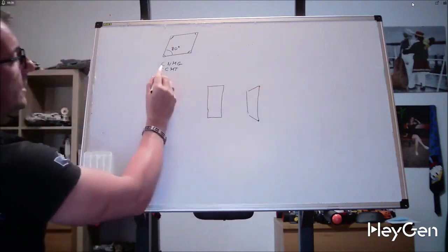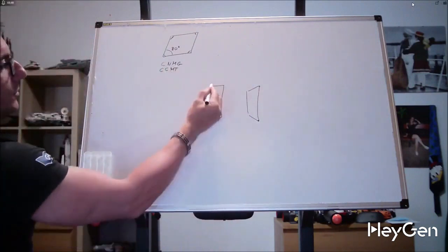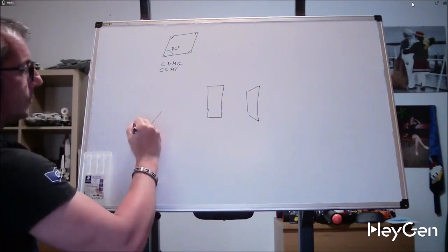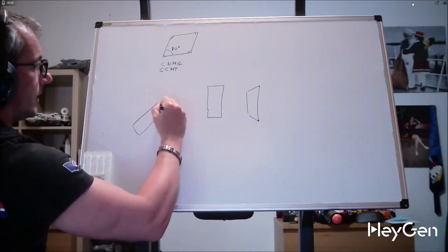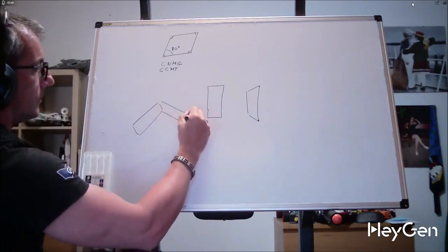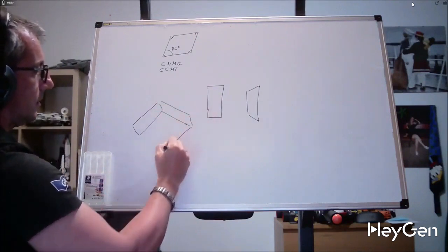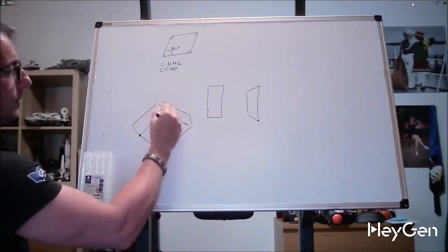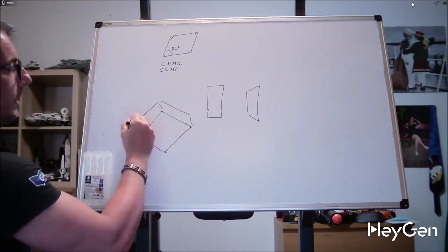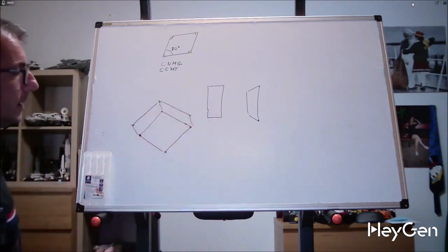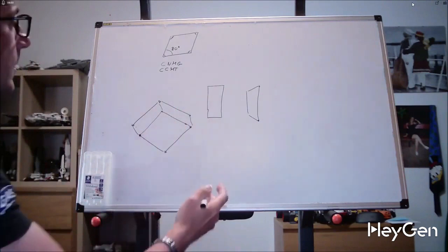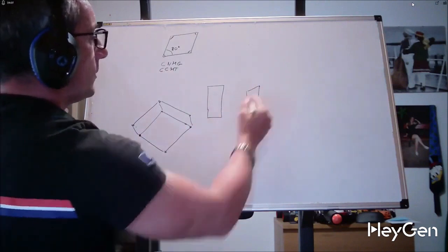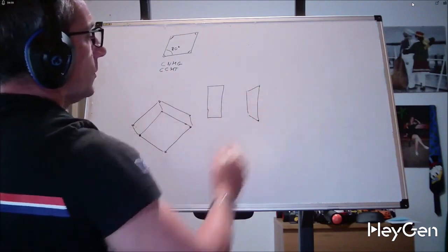So if we look at it in perspective, we will see that we can use 4 cutting edges on this face and just as many on the other, meaning it is indeed reversible. The CCMT, which are called positive tools, is not reversible and can only be used on one face. It goes without saying that this is the best solution for finishing and this one for roughing.